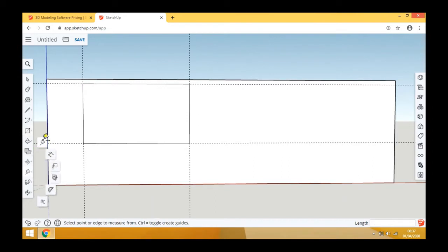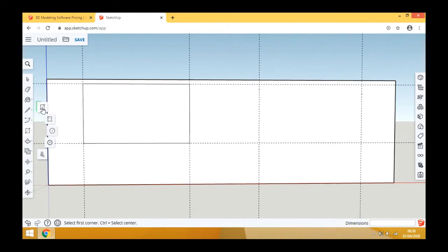Back to the tape measure tool to create our second screen. Exactly the same method. Go to the edge, click once, pull it along, I type 4 foot return, then I do the same 12 foot return, and there we've got our screen. We've already got the 6-inch header and the footer. I hit the rectangle again, place it in the corner, drag it down. There we go. That's our 2 screens.